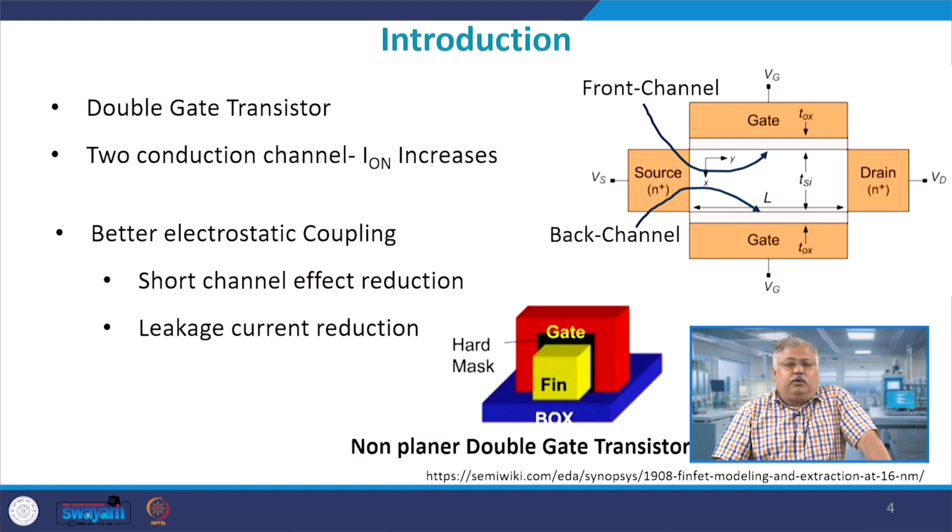Till now, if you look closely at the way the lecture was proceeding, we were all assuming that the device is a 4-terminal device, so there was a gate terminal, a drain terminal, a source terminal, and a body terminal. What was the body terminal we were referring to? The body terminal was primarily the substrate terminal, and it gave me control of the threshold voltage of the device. We had looked into it in detail in our previous lecture.